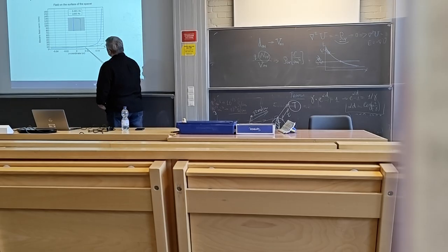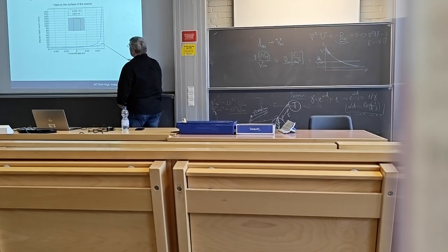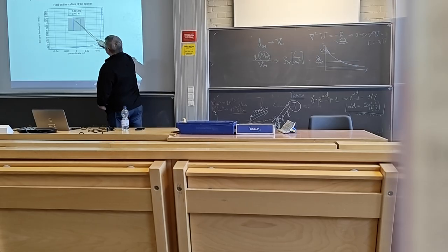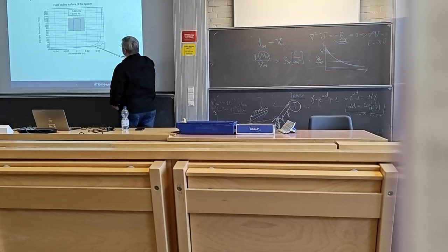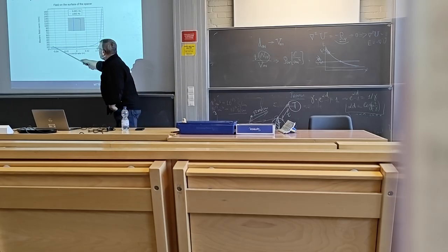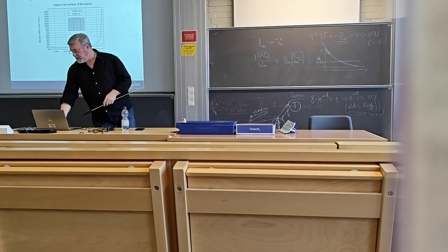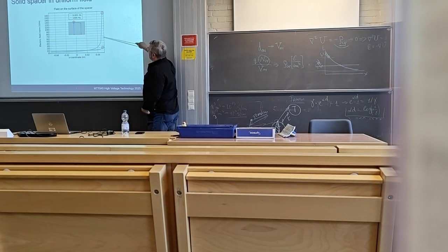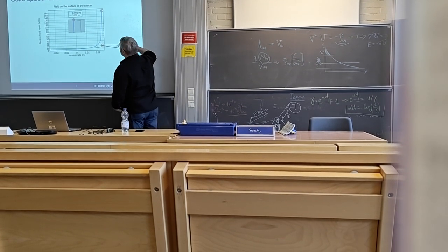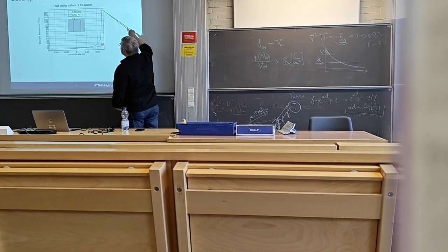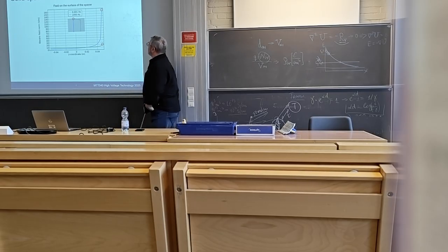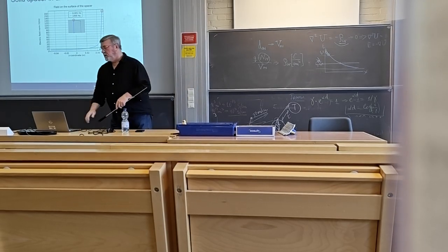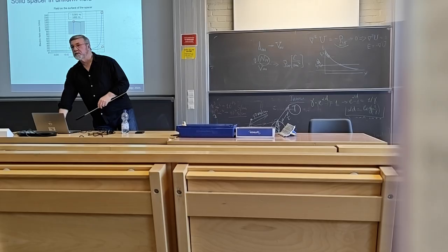High frequency and low frequency on this line. Looks like that. So in the middle of the spacer, not much happening, but on the triple junction, it's a disaster because the field difference is 20 and 160 with 80 maybe. It's almost 10 times, 9 times difference. So when you design these things, insulation, you have to consider this somehow.